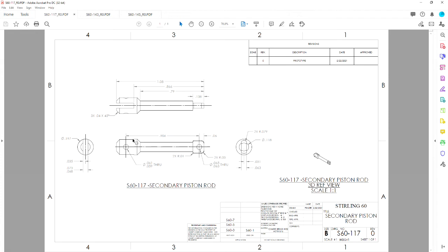We'll put this chamfer in, we'll come across, put another chamfer in, come down to the center line, back to origin, and then we'll probably put these two fillets on as sketch fillets, because we could make them at the end, but for this it's pretty straightforward. So if we needed to uprev the part, we would only have that one sketch to uprev the entire profile. Alright, so let's go to SolidWorks.